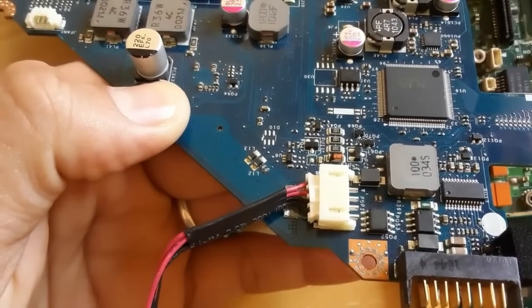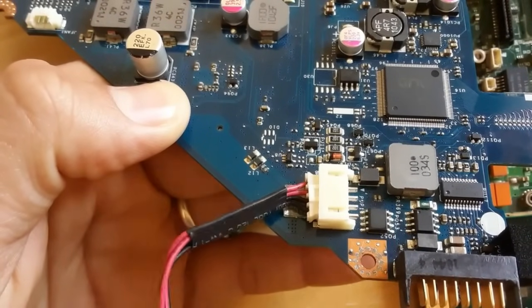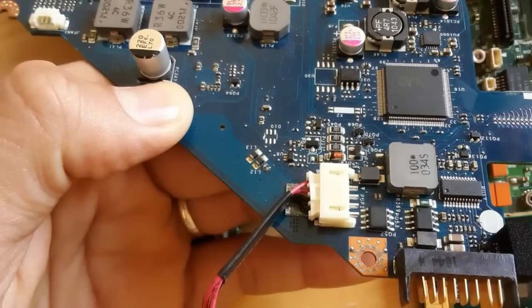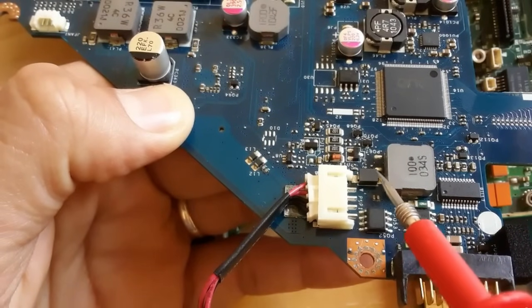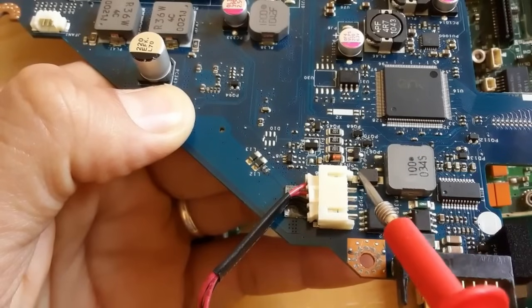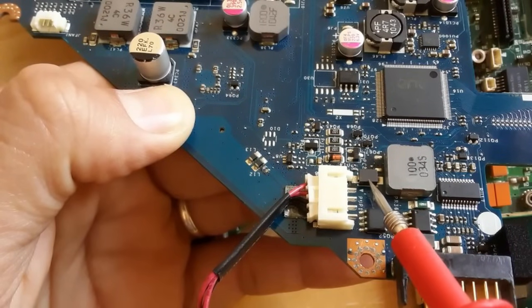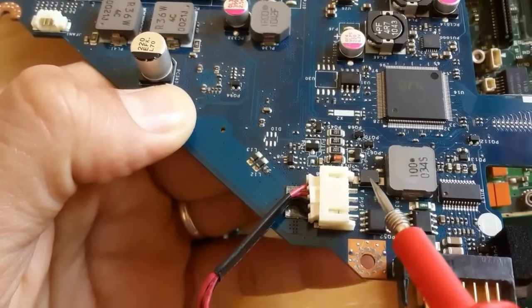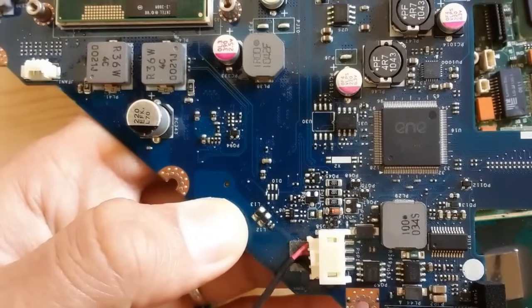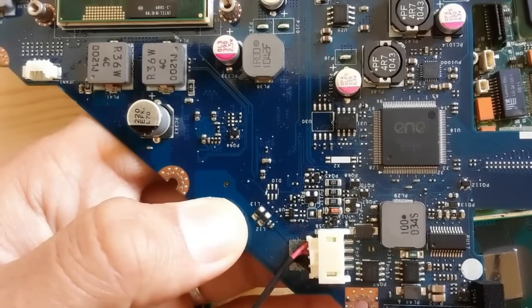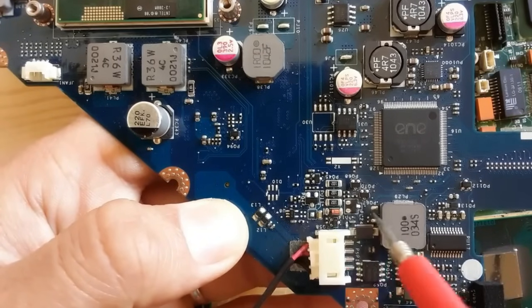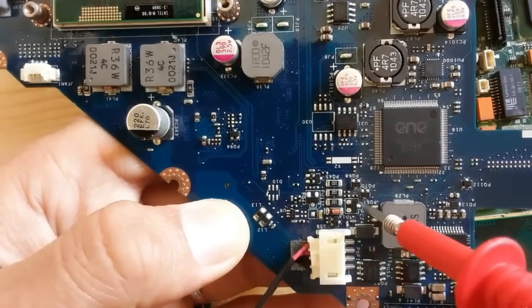Here also, as you can see, you will always find a diode in the protection components. So this is the power jack connector. Here we have the diode. The diode is always an important protection component in every motherboard, because one side of the diode, the anode, is connected to the ground and the cathode is connected to the power rail. When there is a problem, the diode will be shorted to the ground in order to protect the whole motherboard.